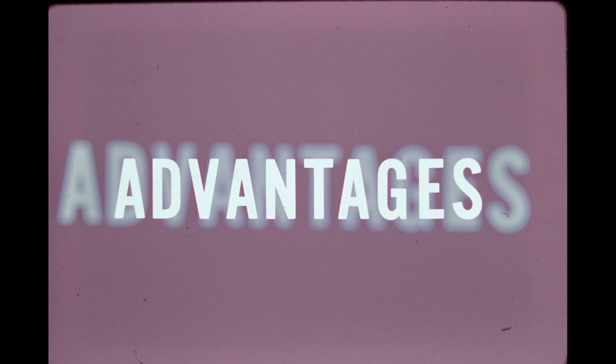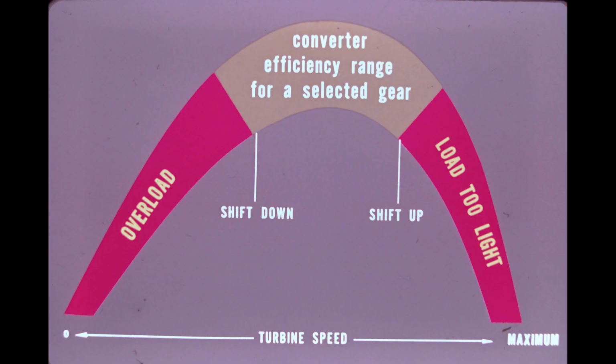But advantages don't stop there. For instance, because there is no mechanical shift in the torque converter, a smooth change from one torque-speed ratio to another is automatically provided. The converter, when used with a POWERSHIFT transmission, enables the operator to match load demands with a minimum of shifting.